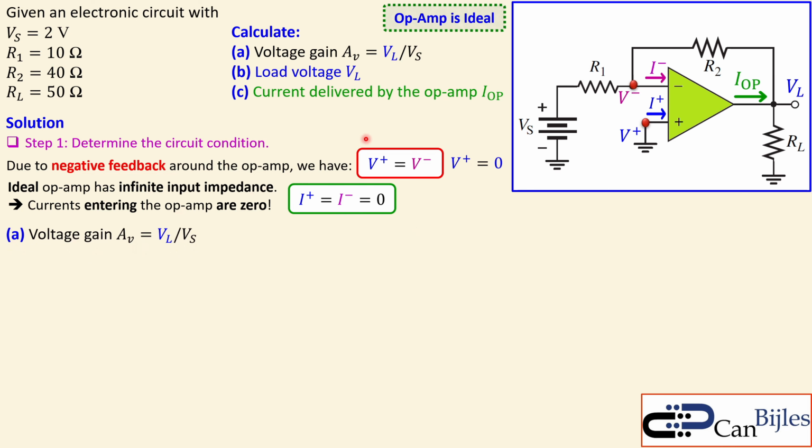Now, for the voltage gain, which is the load voltage over the source voltage, all in DC, we need to first write down the circuit equations using Kirchhoff and Ohm's law, etc. We have discussed this in great detail in the playlist on electric circuits. So first, let's define the current directions. For R1, I define this direction, so plus and a minus sign. The current goes from left to right. For R2, I do the same, plus and minus, and the current goes from plus to minus, so left to right. I also do that for the load, from this node to the ground, which is IL.